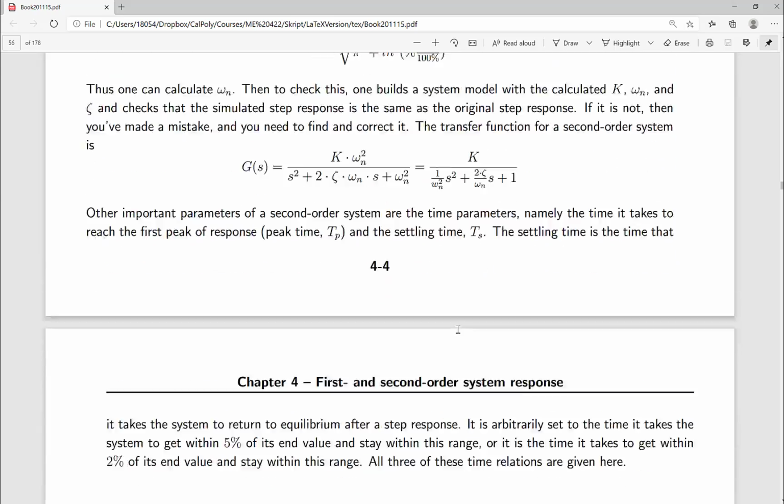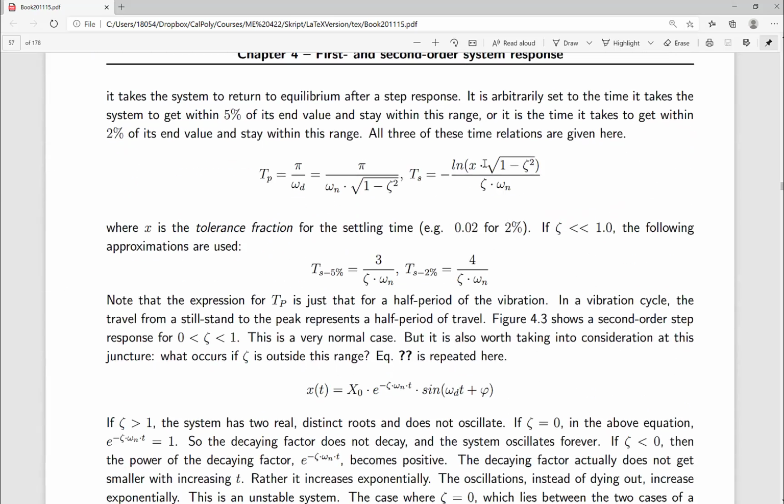And that's actually in this formula here. But what's known and used all the time in industry is a settling time related to a 5% band. So when you go within 5% of the final value and you don't come back out of it again, that's this settling time.